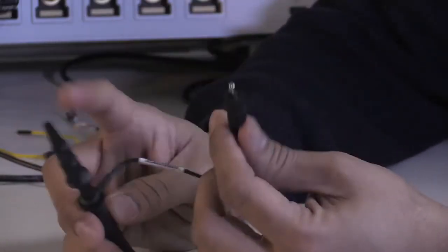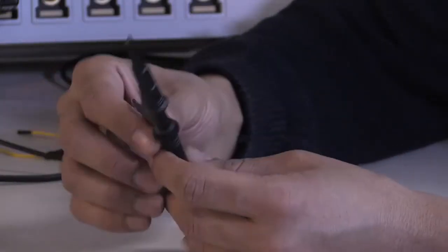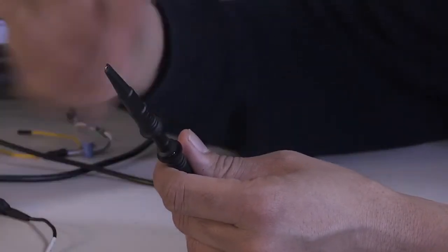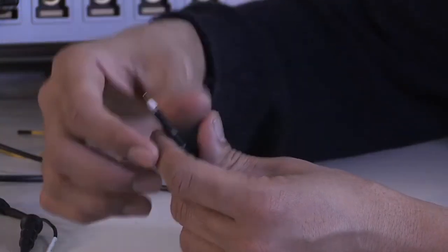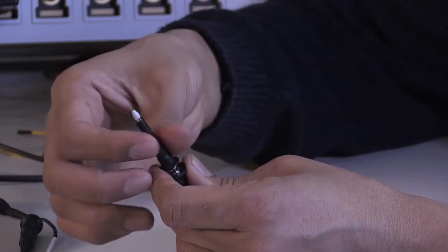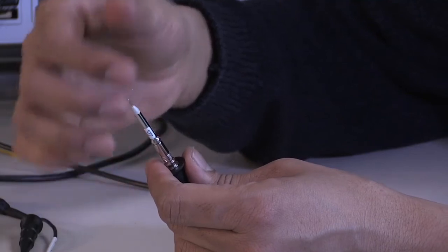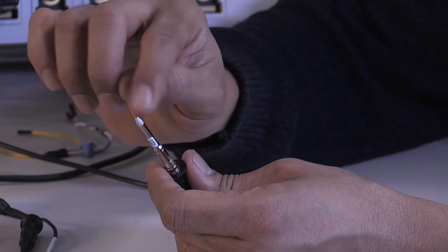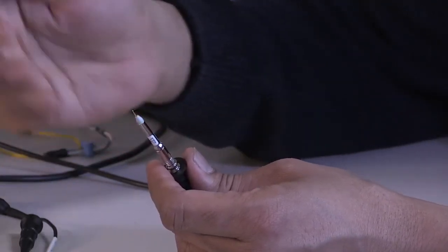We all know this is a standard probe, and one of the challenges is obviously the ground loop, right? So as soon as you have this ground loop, there's not much you can do with this measurement, right? So this has to go. This is a no-go. It cannot work, right? So a lot of ways people solve this challenge is by using those spring connectors, and you essentially take the sleeve off and put the spring connectors on top of this, right? That's good. It solves some of the problems, but you still have pickup problems because you still have that small ground loop as well as ways the signal can inject into it, right?